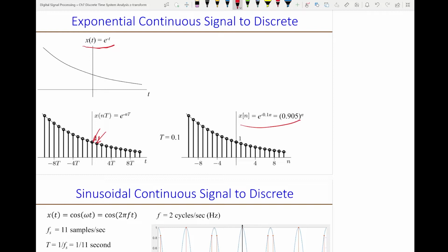The sampling theorem says the following. You check the bandwidth of the signal, or sometimes the maximum frequency in the signal. Then the sampling rate should be equal or larger than twice the bandwidth or twice the maximum frequency in the signal. So for example, in speech, the maximum frequency in speech is 20,000 hertz. So the sampling rate should be 40,000 or more.